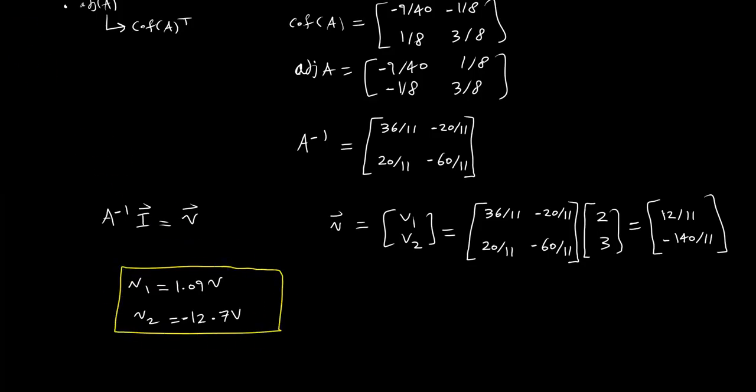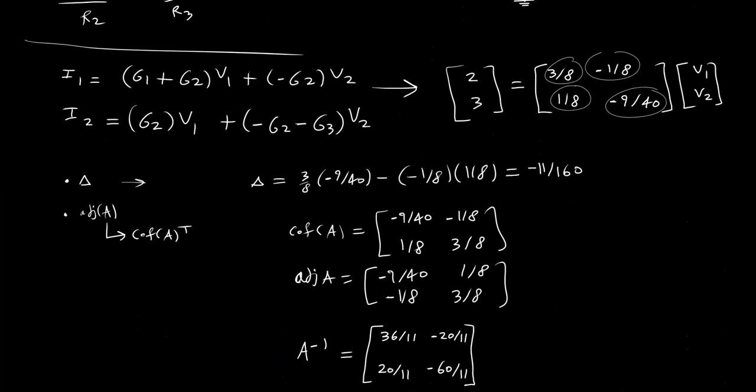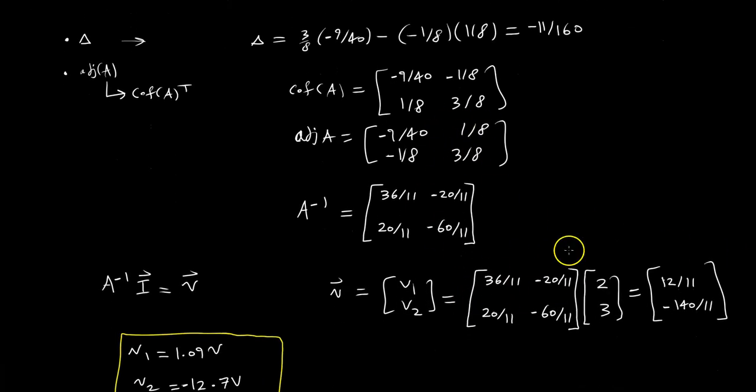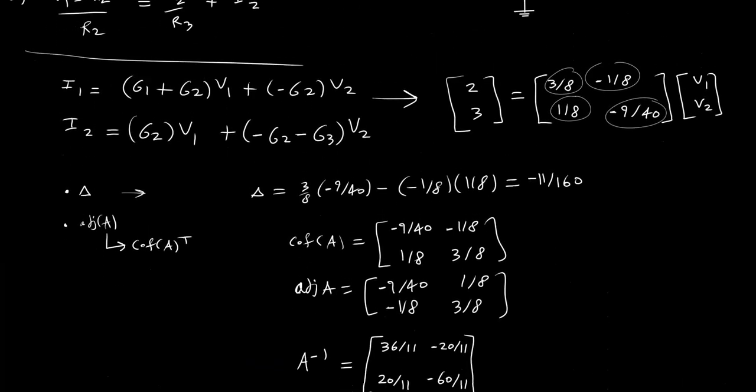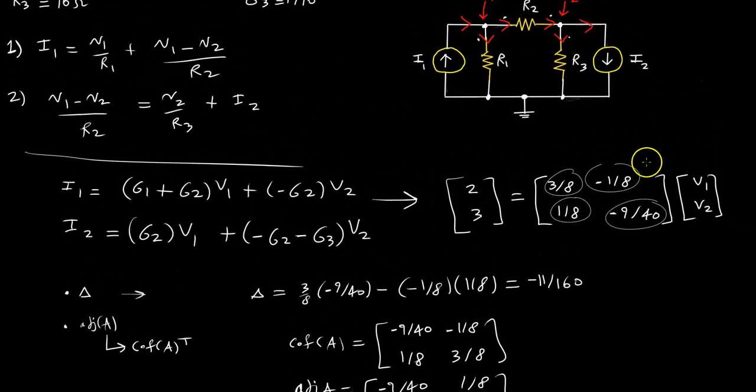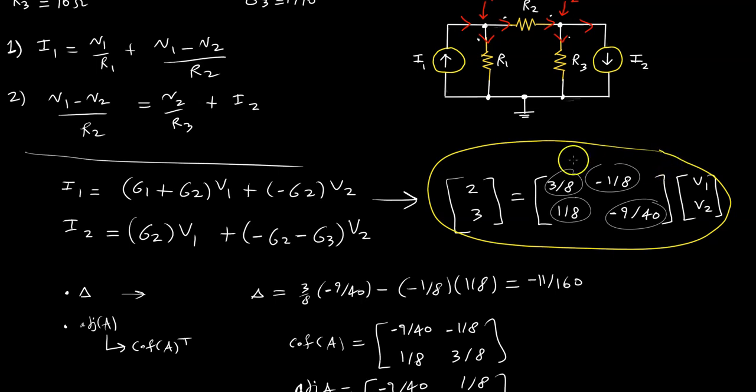Now do note that MATLAB is not going to check if we did KCL correctly. All it can do is check to see if the matrix equation was done correctly. Because if you made any mistakes up to getting the equation in this form, MATLAB is not going to be able to tell us that. So essentially what that means is really pay attention and make sure that when you put your equation into the matrix form, every entry is correct. That's the most important part.